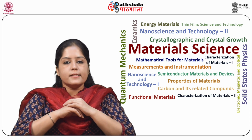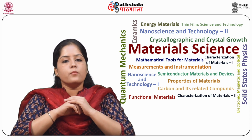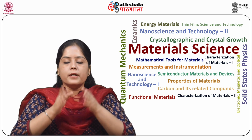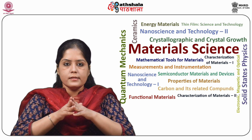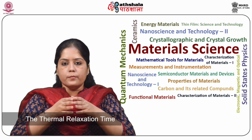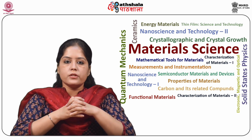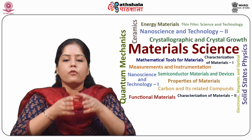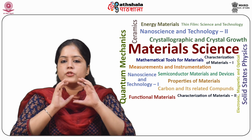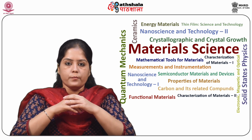So students, let us summarize what we have learned in this module. First, the MOS capacitors biased in deep depletion region, which are the building blocks of charge coupled devices, were discussed. Second, the thermal relaxation time is the interval between the initial creation of the deep depletion region and the formation of the inversion layer. So in a CCD, the information is in the form of charge. It has to be transferred well before the thermal relaxation time.